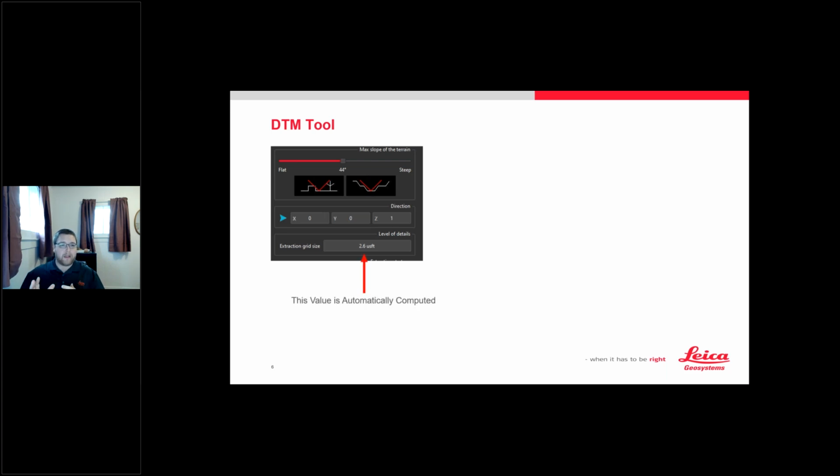First one, the slope of the terrain, that's going to vary. You're going to base that off of what's going on with the data set that you run. Even if you have that turned up high, usually if you have your other settings set well, it's going to avoid some noise or vegetation. We have a setting that'll adjust for that. So I tend to keep it turned up a little higher, just to hopefully catch my tops of banks and bottom of banks right out of the gate.